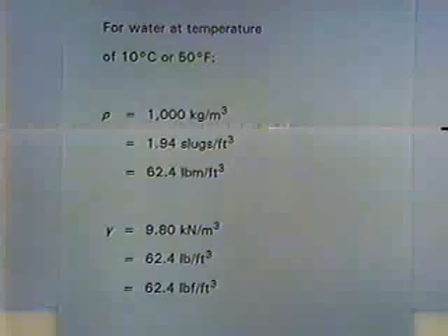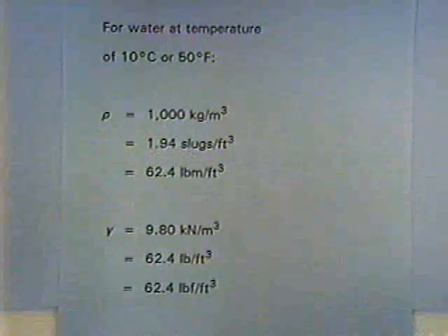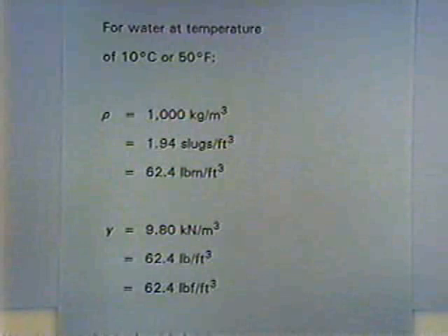That's good. Okay. The properties, including density and unit weight and other properties as well, of course, vary for different fluids, for oil and gas and different gases and water and so forth, but they're also a function of temperature. And often in a problem statement on an exam, they'll not be given a temperature. Of course, if there is a temperature given, you'll want to use that temperature and go to the tables in the reference manual, or the tables that are in the back of just about any of the references that you'll have in fluid mechanics and hydraulics books, and read out the properties as a function of temperature.